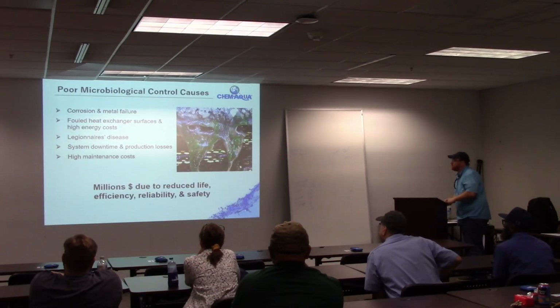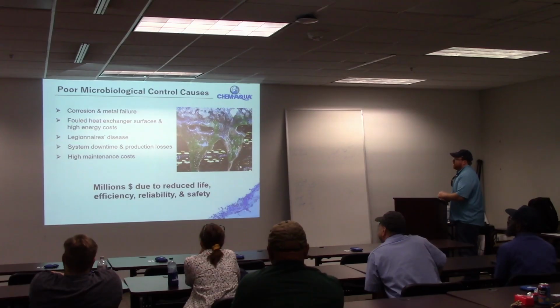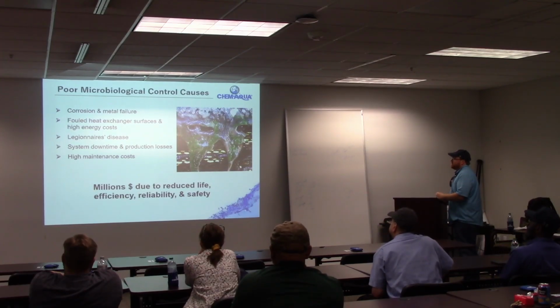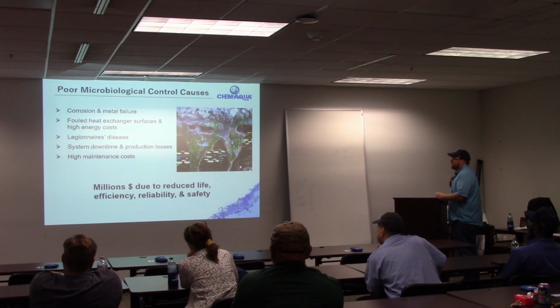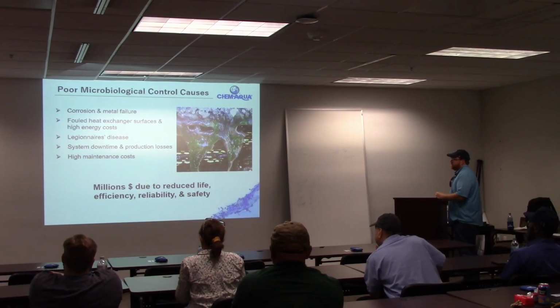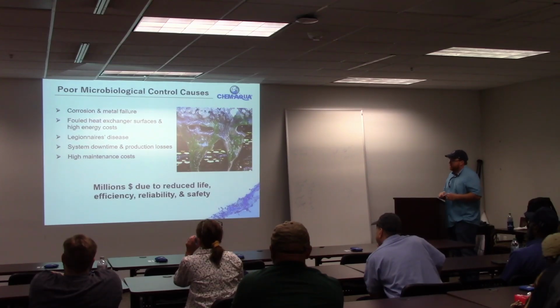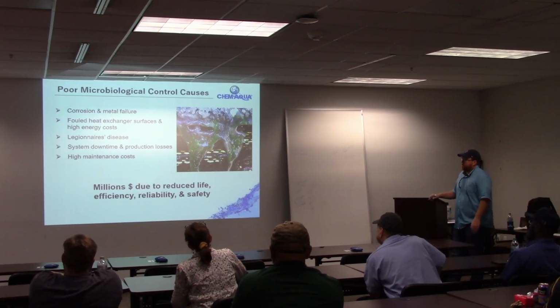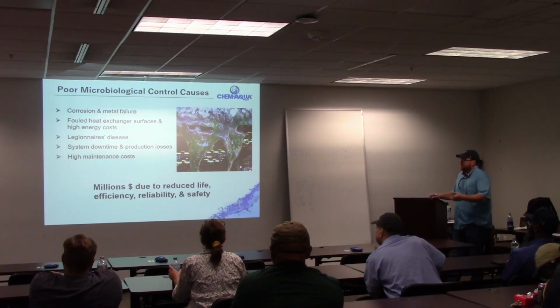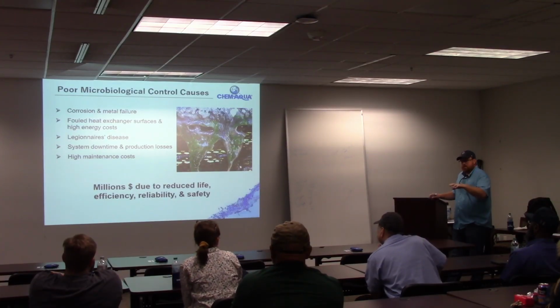We kind of talked about this a little bit earlier. That's a really nice big slug of bioslime there. That can cause a lot of issues like we talked about: fouled heat exchanger surfaces, which causes poor heat transfer, and corrosion and metal failure, especially if you have biofilms forming underneath deposits that are eating away at the metal underneath. We've all heard of Legionella and Legionnaires' disease. That's something we're not going to really get into too much today, but obviously that is a concern, especially at healthcare facilities.